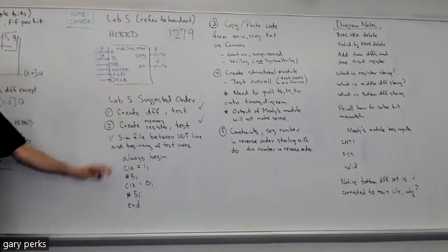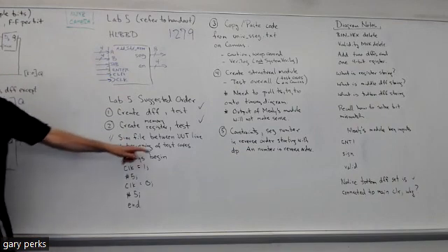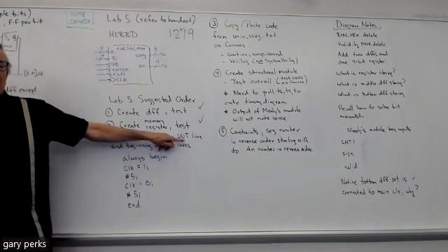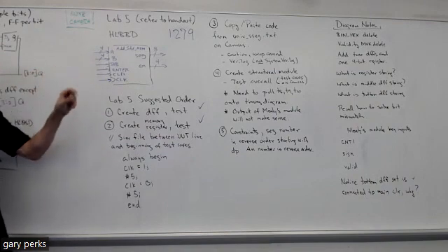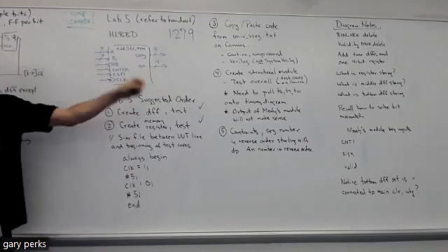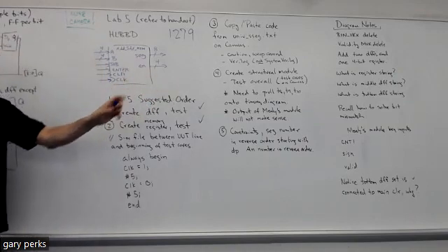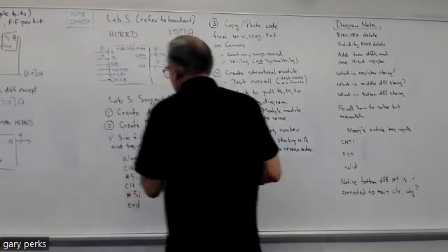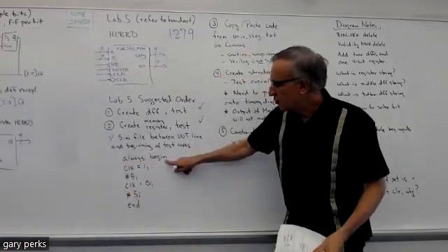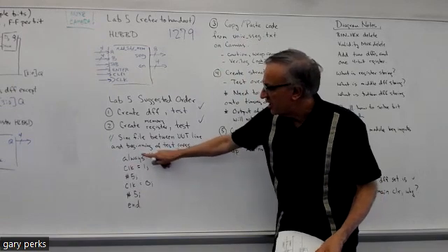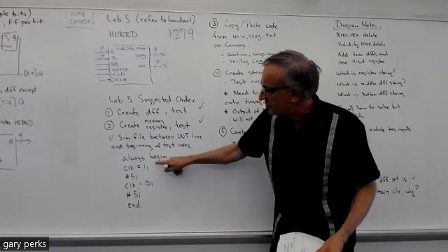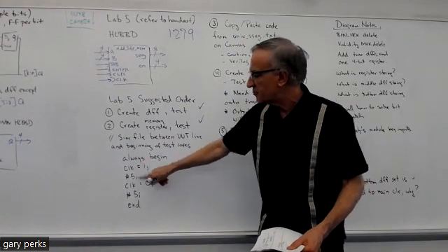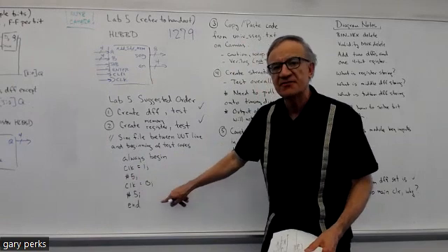But now, since we have something that has memory, a flip-flop and a register, in your sim file, after the UUT line, where you put the file you're going to test, the unit under test, and you make all your connections between the design source and the sim file names, in between that and where the test cases begin, you want to put this code right here. Always begin, here's the end for the begin, and then within the always, you have the following: clock equals 1, then number sign 5, and clock equals 0, then number sign 5.